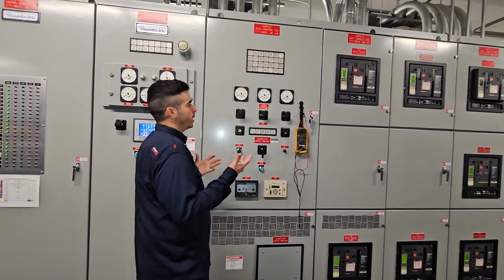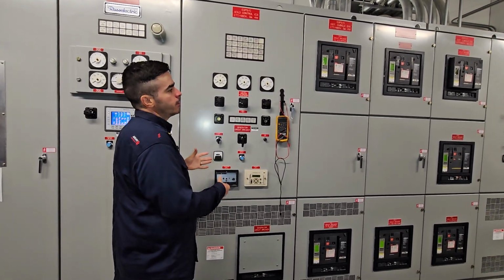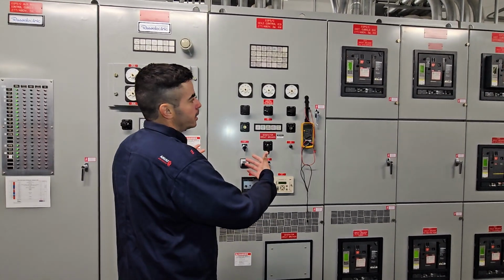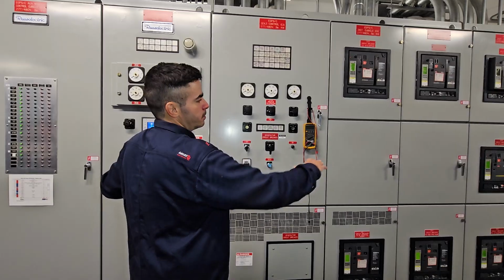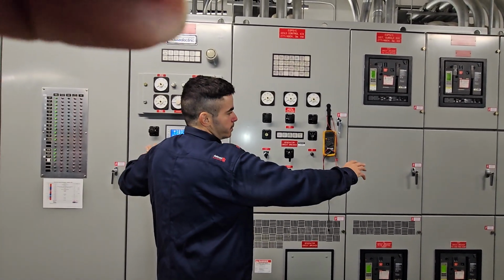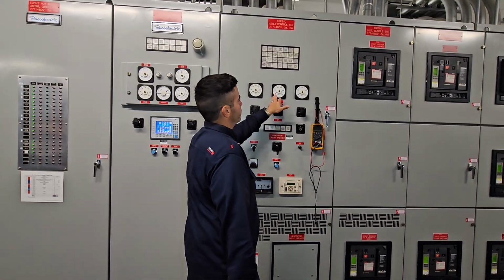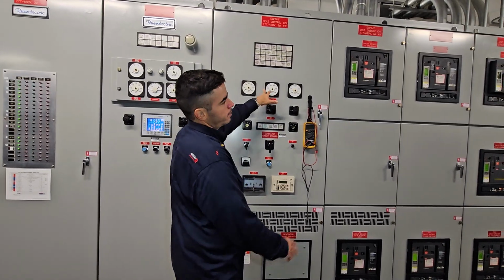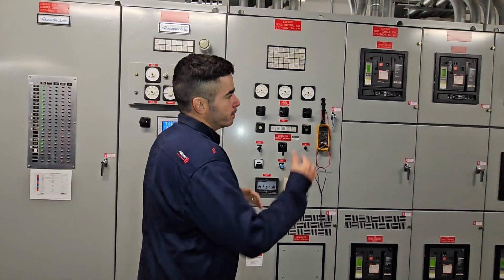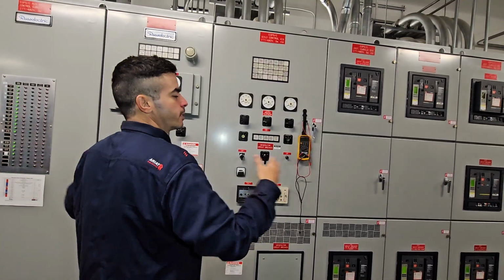If we only have one generator on, the full amount of load that we have connected to the bus is going to be connected to that generator. If we have more than one generator, in this case we can only have two, then the load should split between them. We have some models that will control the load sharing, so they share evenly. You can see this when they are both connected in the kilowatt meter. You can see, okay, that one 500 kilowatts, this one 500 kilowatts, we're good. If those numbers don't match, if we have like 1,000 kilowatts on one and the other is like 200 kilowatts, then we have a problem.